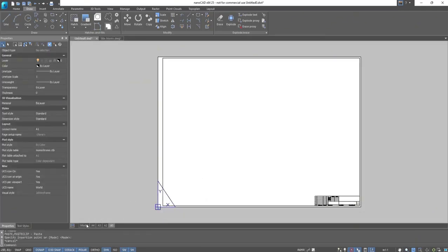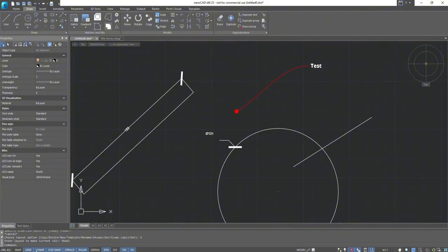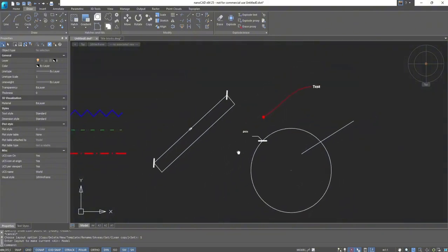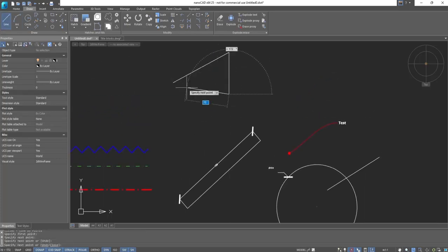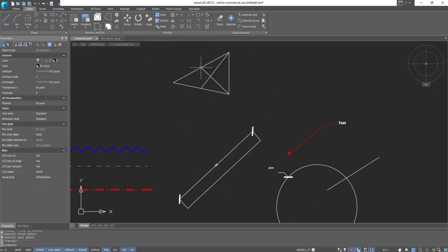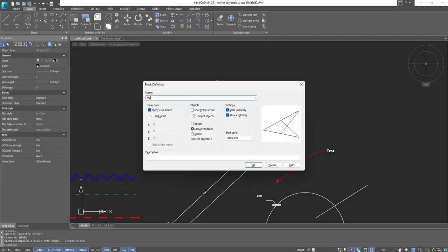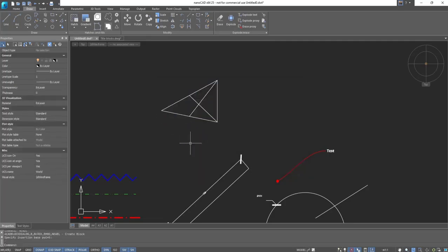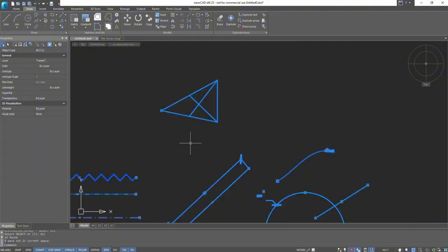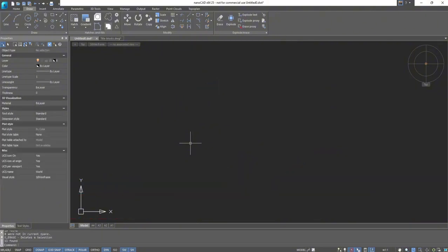Now turn off the grid in the drawing. Let's also add a block to this drawing to make sure it also transfers along with the template. Excellent. Now we will delete everything from the file so that it is empty. For individual cases, you can leave some information in the drawing, for example, an axis grid. When creating a new project, a DWG file will be created based on this template, and this axis grid will already be contained in it.